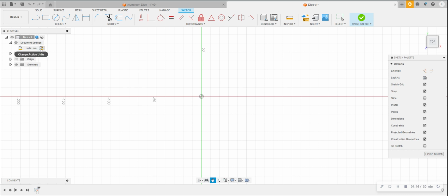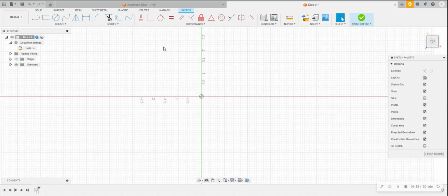So, you can follow my cursor, we'll click this little icon with the pencil, and it gives us this pop-up box. Now if I come over here, I can see right now the unit type is millimeters and I want inches. So I'm going to scroll down and click inches, and then I'm going to say OK.